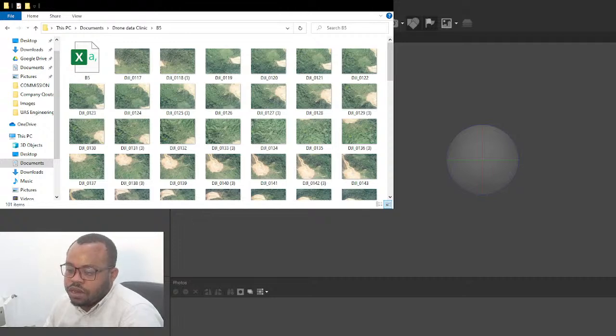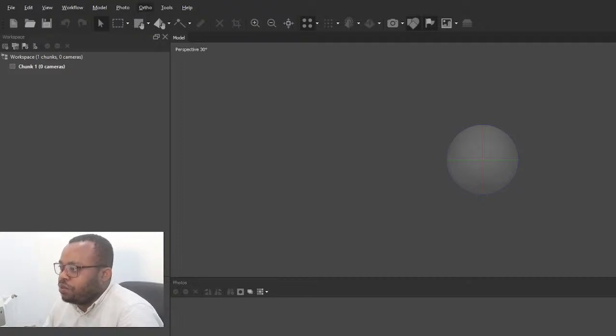What we're going to do next is to go to Tools, and on Tools, we go all the way to Properties, and we move our attention to the GPU. On this system, I have an external graphic card. Most of your systems, you need to check if you have an external graphic card. And once you have an external graphic card, kindly check this and also check what is down here to optimize your process, and apply.